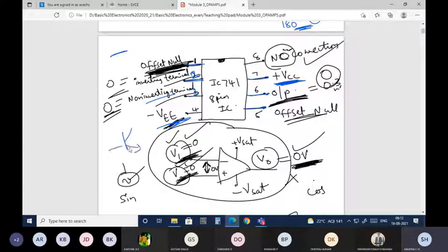Okay, the transistor should be biased in the proper way so that conduction will happen and it will be able to amplify the signal. That is why we provide the biasing. So minus V and plus VCC are nothing but the biasing inputs. The biasing inputs in the sense, you need to provide proper voltage between the input and the output so that it will amplify the signals properly. So that is what the biasing is. So plus VCC, minus VE, or such kind of input voltages, and the 8th pin will not connect anything.